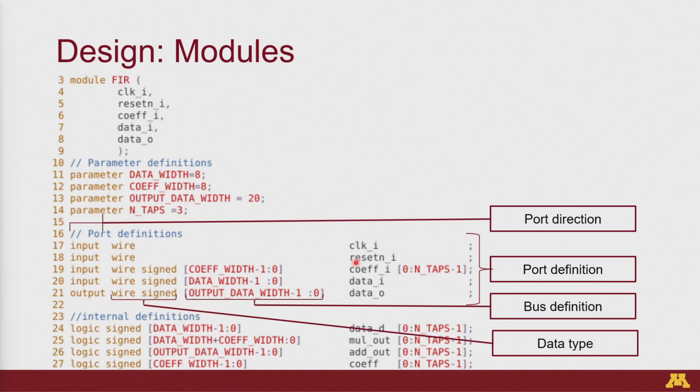Yeah, and one follow-up question. When I was looking at the declaration of the packed and unpacked, for packed you go from the top, 7 down to 0, and for unpacked you go from the low 0 to the max. Is there any convention for this? This is a convention and just style. Actually, if you want, you can go 0 to the max in both cases, but this is just a convention. I would say it's more of a coding style thing. There's no reason why you should go from top to bottom.